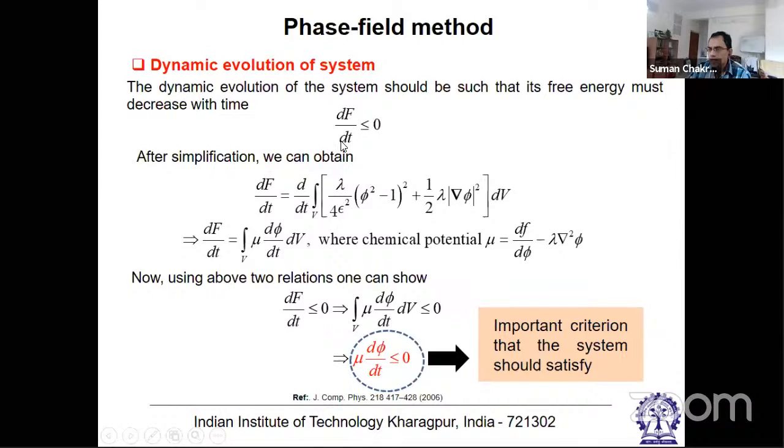So if you express this in terms of Eulerian variables, it will be capital D dt, or total derivative. But here up to this, since it is not expressed in either Eulerian or any special type of variable, we just preserve this small d dt. But when we express this in terms of Eulerian variable, we will use the total derivative.